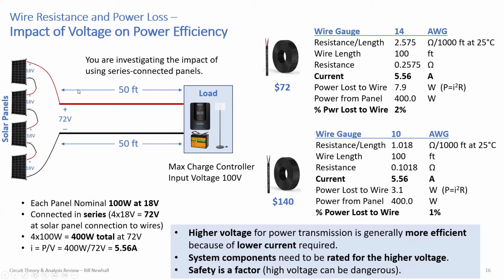And there are different considerations when you have solar panels in parallel. If they fail open, let's say one panel fails, you lose 25% of your power availability, but the system keeps operating. Here, if you lose one of these panels and it gets hit by hailstones and one of them fails as an open circuit, your whole system is down. So this is more power efficient, but can be more vulnerable. Okay, so lots of trades to consider here.